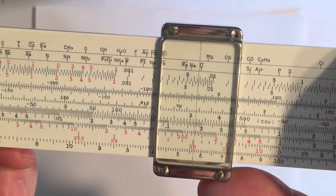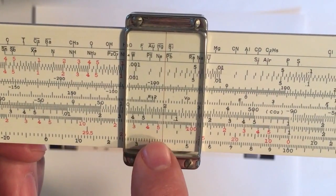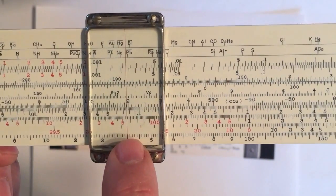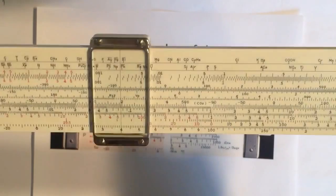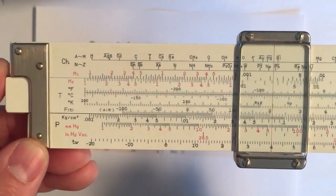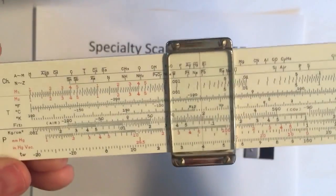If you want to look at 40 degrees, go up and look at whatever units you want, millimeters of mercury or inches of vacuum. You can get direct readings of whatever vapor pressure water is at that temperature. So all in all, a very useful tool, even for today. If you don't have a computer or a spreadsheet handy, or don't have these molecular weights or steam properties at your fingertips, this would be a good secondary slide rule to have on hand.